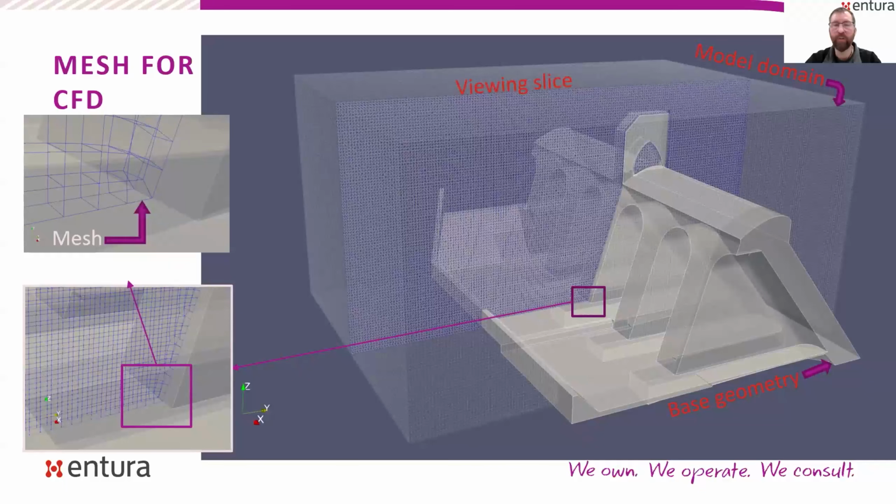And so here's a picture of a typical problem that I might be solving, with flow over a dam spillway. And what you can see on the right-hand side there is the full geometry. The thing that's interesting is that we start off with the structure and the computational domain, and for most civil engineering applications, the problem is the air or water space around the structure. You're interested in how the fluid interacts with the structure. So in that regard, the mesh fills up the space around the structure.